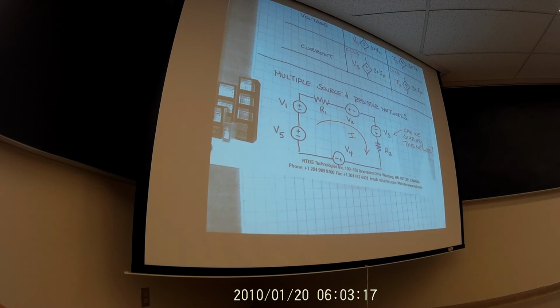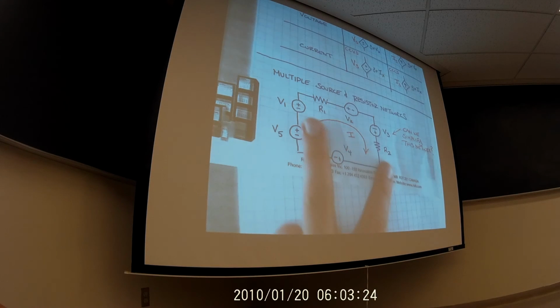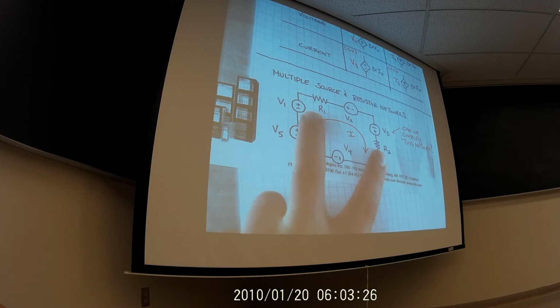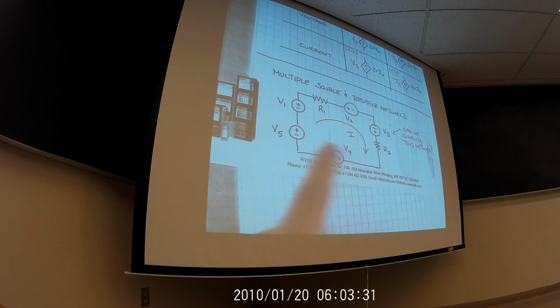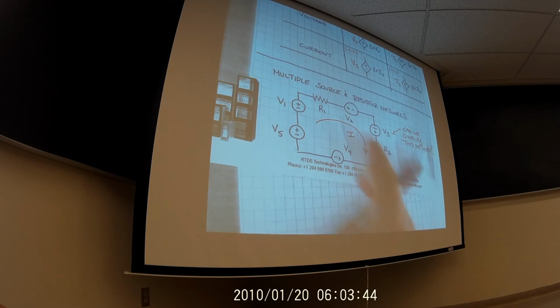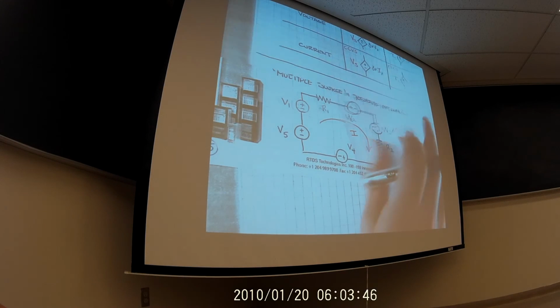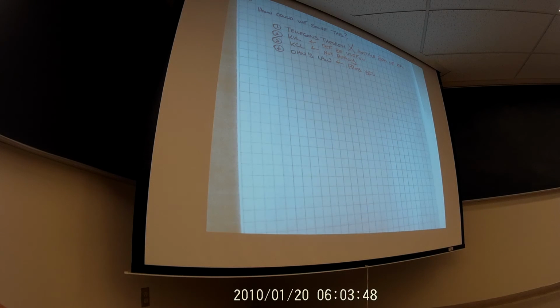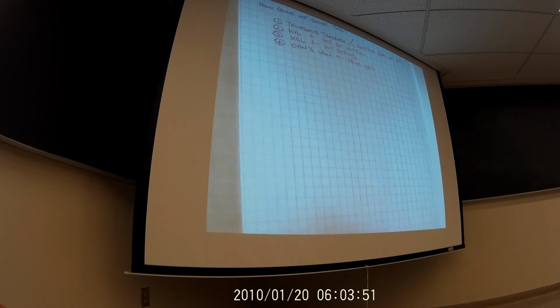We know that resistors that are in series can be summed together. Now, these two resistors are not really in series. The trick, though, is that if we're trying to solve for the current flowing through this loop, we can shift the order of things around however we want. That'll become evident when we write out our KVL. So we can move these two to be in series. But I don't want to skip ahead too much.